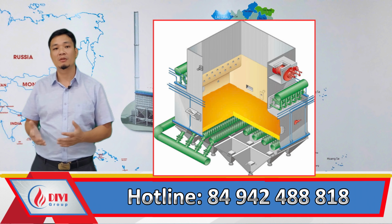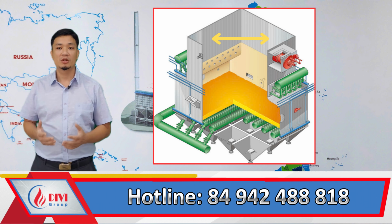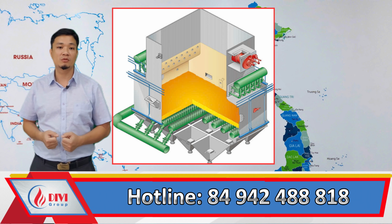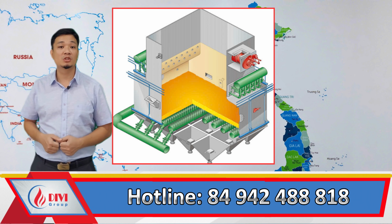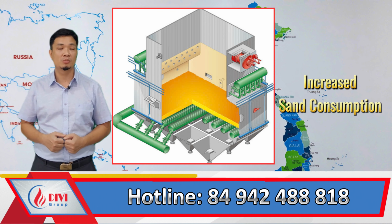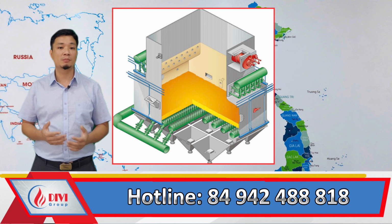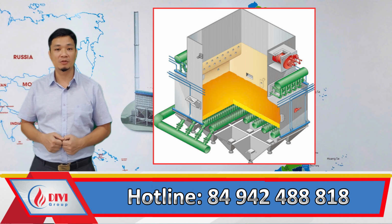The large size of the furnace also increases the consumption of construction materials, especially metal, making high-capacity BFB boilers more expensive to fabricate compared to CFB systems. Furthermore, with low flue gas velocity comes the need for a larger furnace cross-section, which in turn requires a greater volume of bed sand. Distributing fuel evenly across a wide combustion surface becomes technically difficult. These are the key reasons why BFB boilers have more limited capacity scalability than CFB boilers.